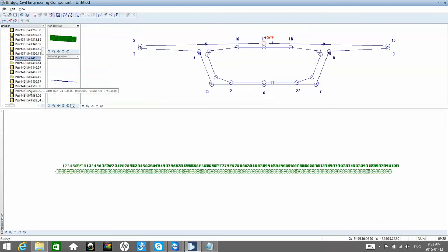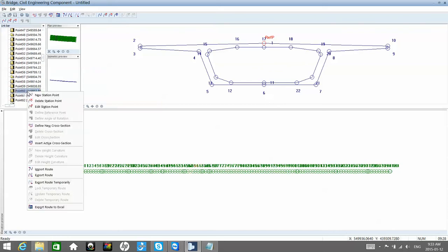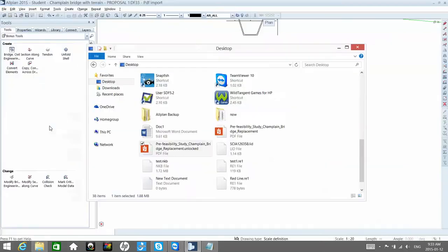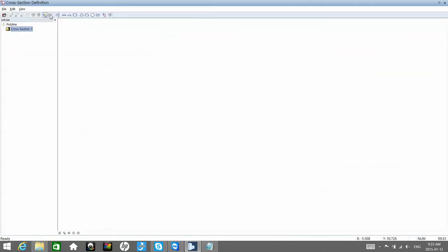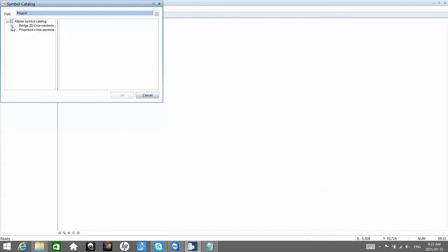So now we're going to do it to look as in the picture. So in cross, I said in 60, I'll provide the second cross section, and then starting 38, it will do the variation. So it won't do the variation from the first point, but between 2 points I pick. So define new cross section for points 60, it will be cross section 4.